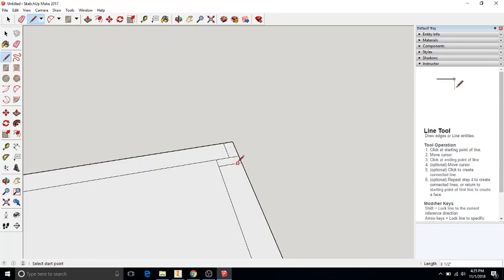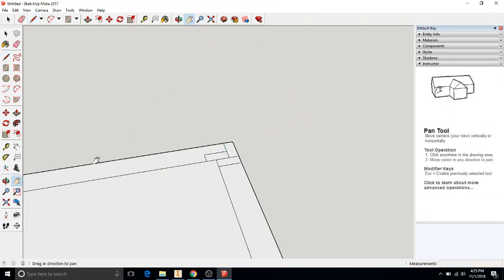And lastly, you've got the end of your board, so you do the end of the wall, and then establish the hanger for the sheetrock. Coming over, extending out, make sure we're on that line. 1.5, the thickness of my 2x4, and 3.5. Fantastic.